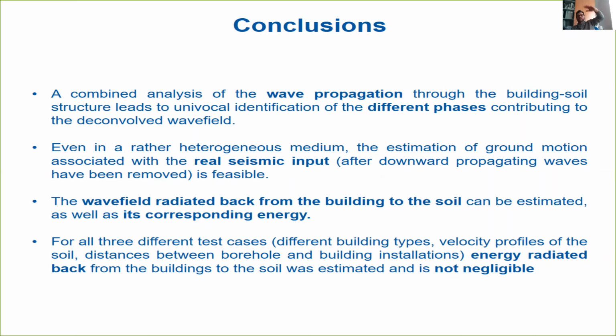You don't want to propagate through the structure something that has also a downgoing effect. You want to only propagate something which is propagating upward, otherwise it would be wrong. But very often this is not done. And it was possible to estimate the wave field radiated back from the building to the soil and its energy. And this quantity, as I showed you, is not negligible, so it can be a lot.